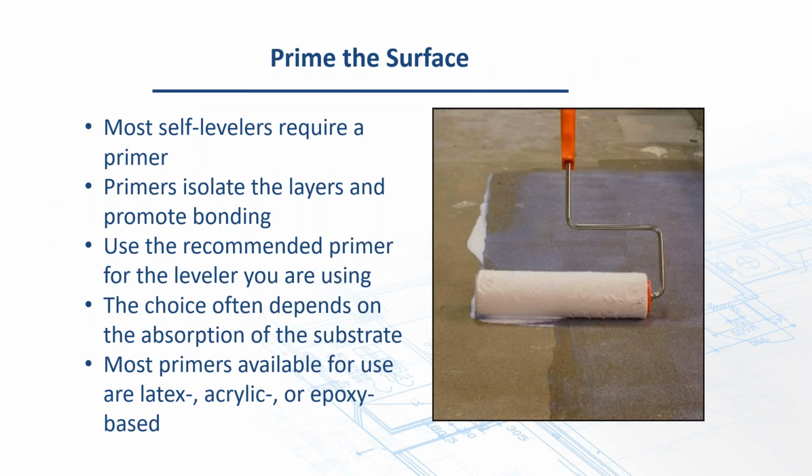Primers are critically important too. We make a variety of different primers depending on the type of substrate it is, depending on the type of leveler that you're using. We can do everything from steel to copper, plywood, of course, concrete. So there's a large variety of primers out there as well. Some really work well on low absorption substrates, like epoxy moisture mitigation. Some won't work so well on that. They need a bit of absorption, like more of a latex based one. So pay attention, it's critically important as far as the type of substrate you've got, the type of leveler that's going on, how thick it's going, etc.